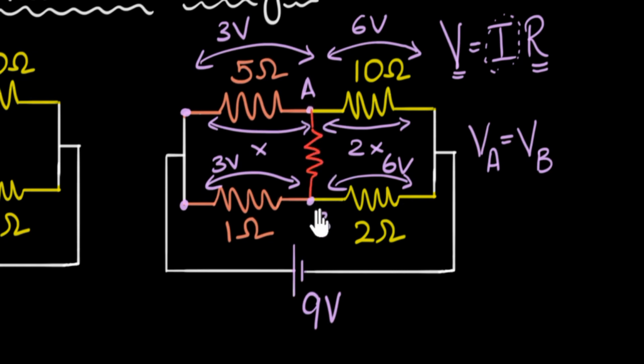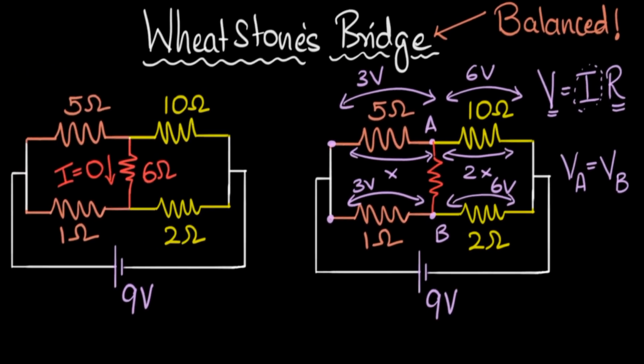So what, you ask? Well, now notice, because the voltages are exactly the same over here, if in this circuit, when it's running, I were to put a resistor in between or a capacitor in between, it doesn't matter what you put in between, the voltage across it is the same. Therefore, these two voltages are the same. Therefore, the potential difference is 0. There is no difference in voltage. There is no potential difference, and therefore there will be no current flowing over here. And that's why a balanced Wheatstone's network has no current.